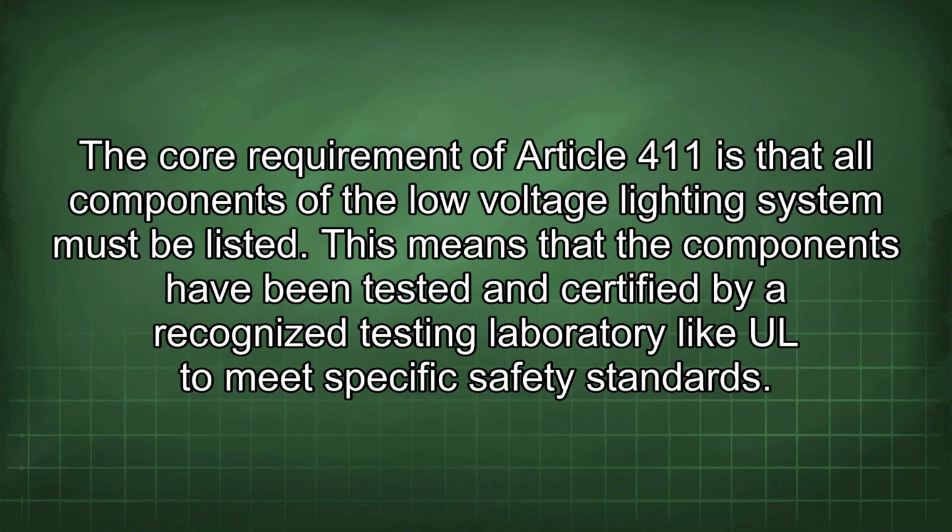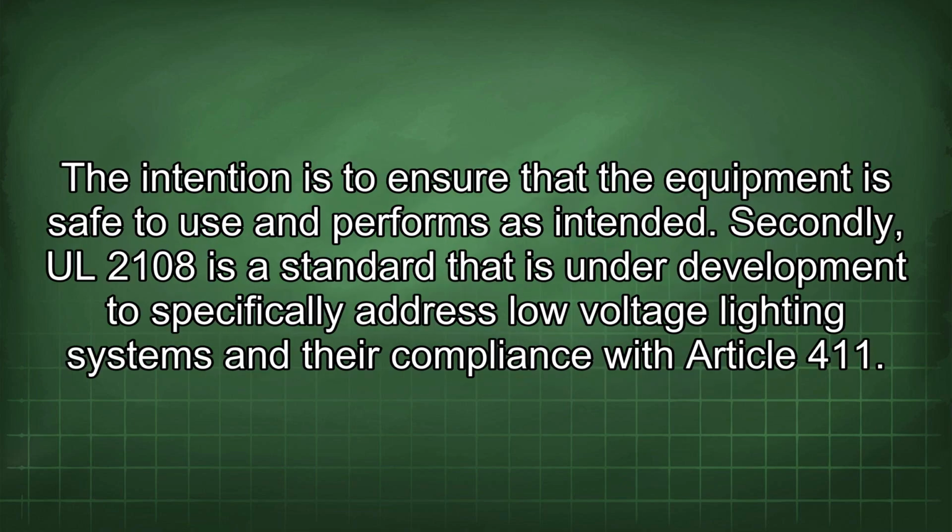The core requirement of Article 411 is that all components of the low-voltage lighting system must be listed. This means that the components have been tested and certified by a recognized testing laboratory like UL to meet specific safety standards. The intention is to ensure that the equipment is safe to use and performs as intended.